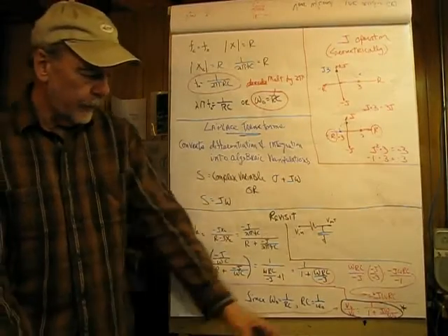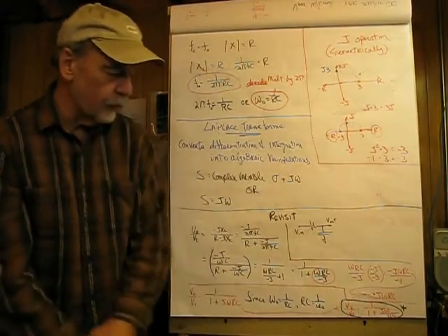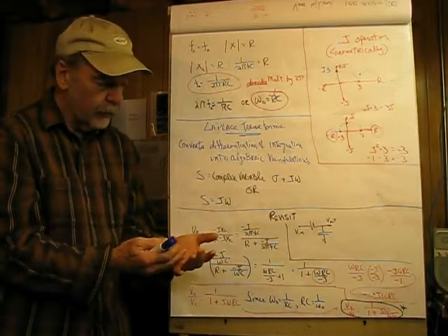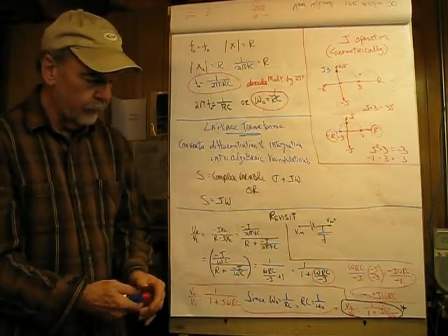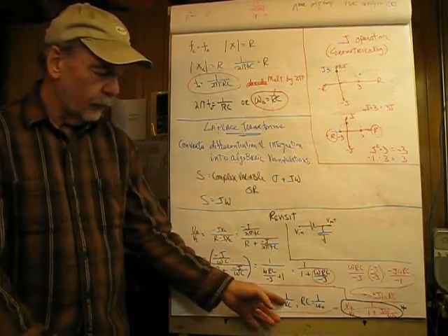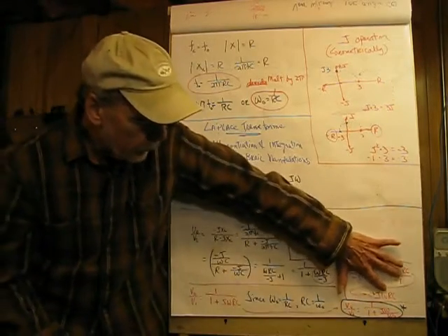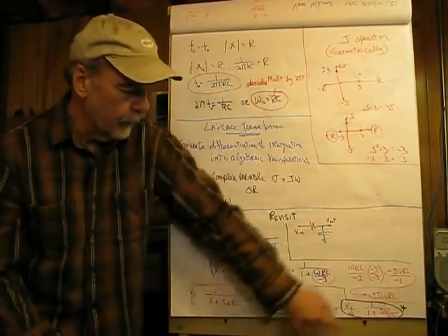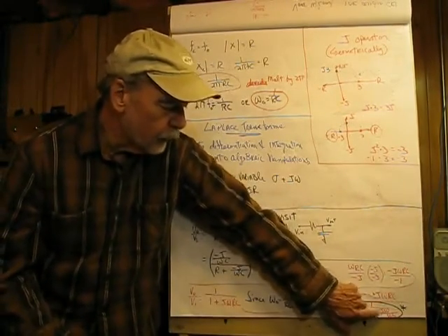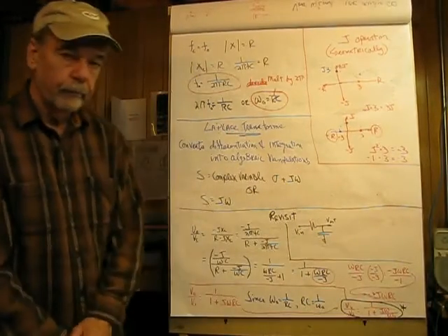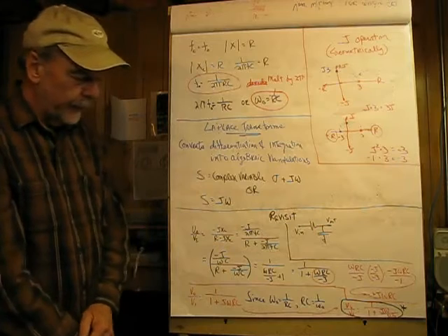So this form has 1 divided by 1 plus j omega divided by our circuit constant for the critical frequency, omega 0. Now let me go through that again. Omega 0 is equal to 1 over RC. So we're going to replace RC with 1 over omega 0. And the numerator would stay the same. Here, j omega would remain in the numerator. So that's the form we would get.